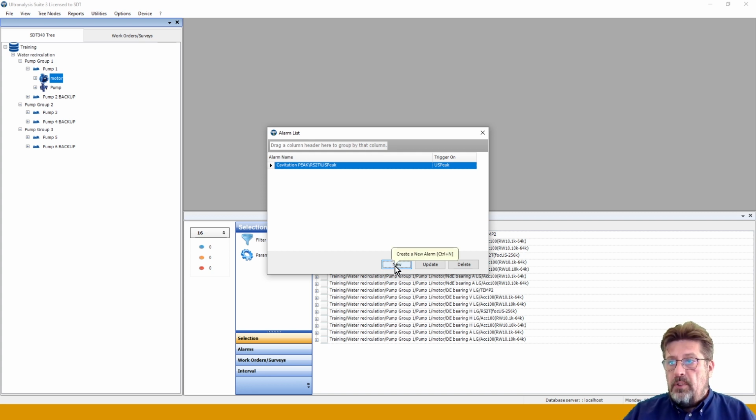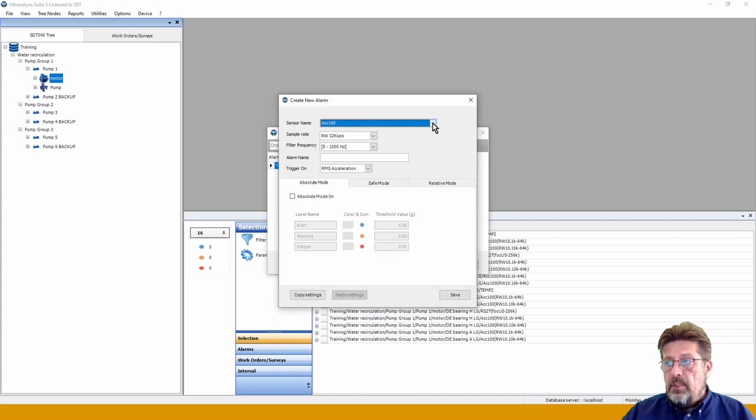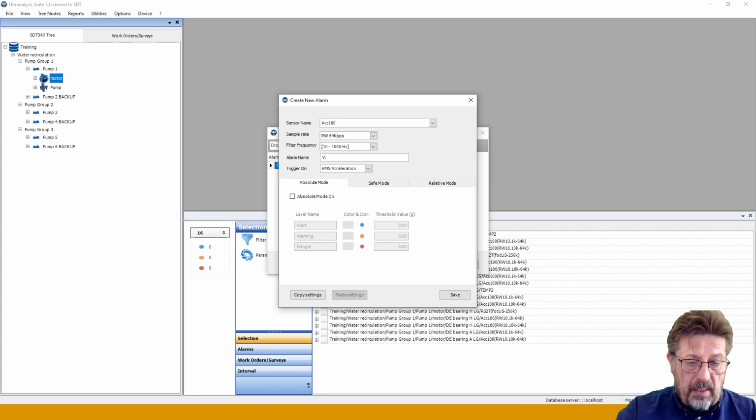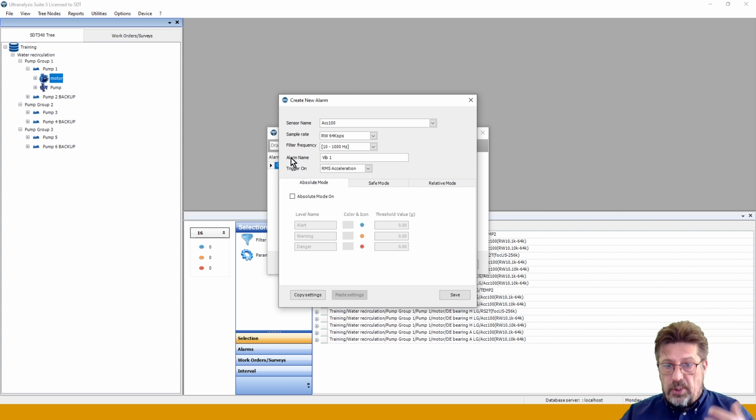I can put another one. I can put this one on vibration, on accelerometer, 64 kilo samples per second. Let's say 10 hertz to 1 kilohertz. Alarm name will be, I don't know, VIB1. Just keep the name that will associate you. I'm just using number 1 just like that. It will associate you what is this alarm for. Or you can say it, let's put it this way.